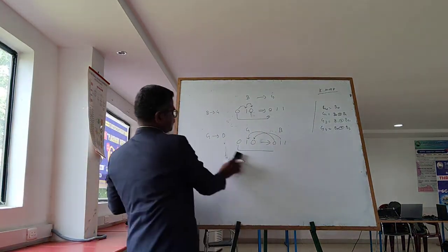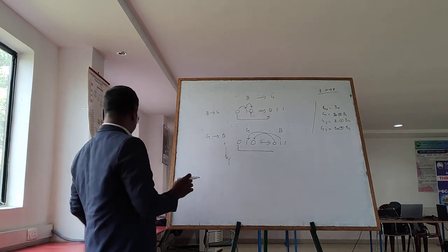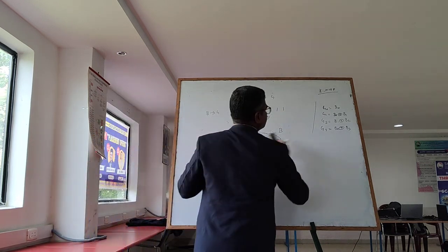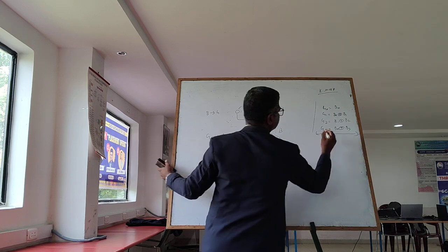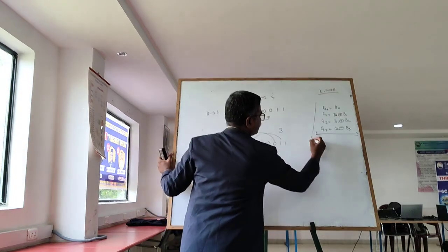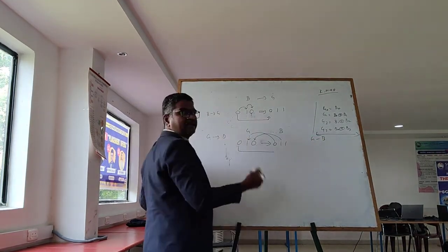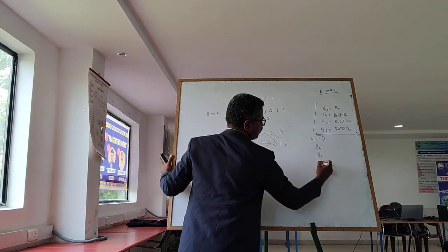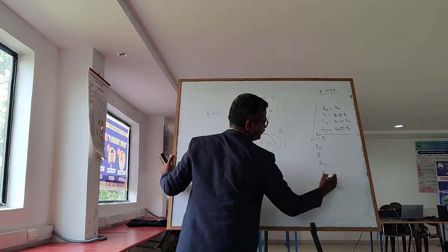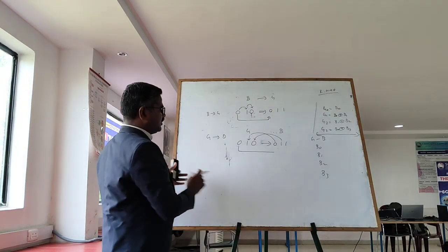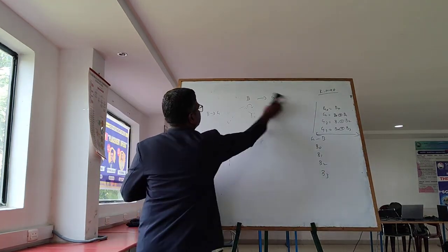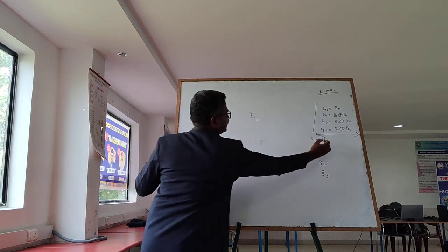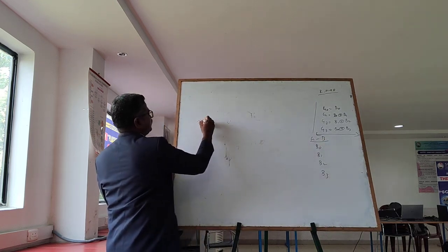The same logic is going to apply here also. So instead of finding G0, G1, G2, G3, in gray to binary what do we have to find, in reverse order? What is B0, what is B1, what is B2, what is B3? Right? Same way, the first rule we have to follow for gray to binary is the truth table.